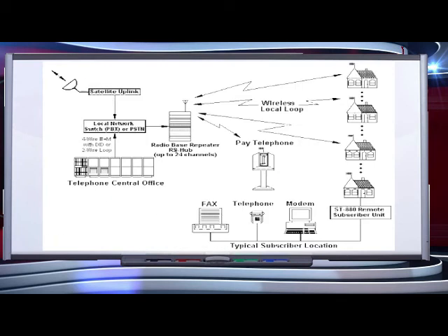Next is WLL, which means wireless local loop. It is meant to serve subscribers at homes or offices. Wireless local loop is analogous with local telephone service but much more capable. A WLL system serves a local area by deploying a multi-channel transmit or receive base station that is within line of sight of the intended customer.